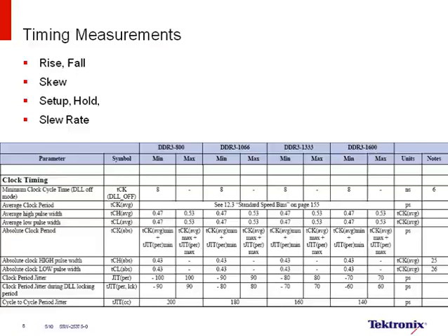In general, my advice is to understand the measurements, the root cause of the measurements, and how they're performed. But for DDR, the measurements themselves are really not that complex. They're really essentially a whole bunch of different skew, setup, and hold timing measurements.